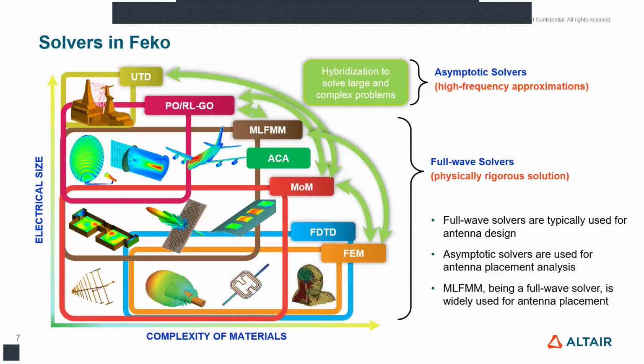Now, when it comes to the solvers available in FEKO, as you can see here, almost all the popular EM solvers are available within FEKO. So by default, if you don't specify to use any solver in FEKO, it will always use method of moments. So that's the default solver. But apart from method of moments, FEKO also has finite element method, finite difference time domain, adaptive cross approximation, multi-level fast multipole method, physical optics, ray launching geometrical optics, which is also called shooting and bouncing rays method, as well as uniform theory of diffraction.